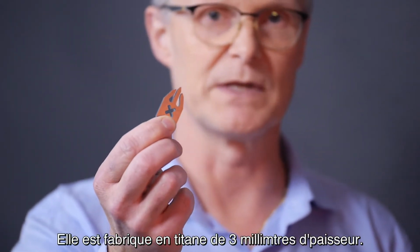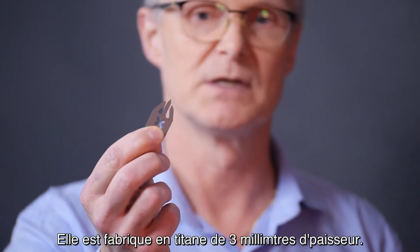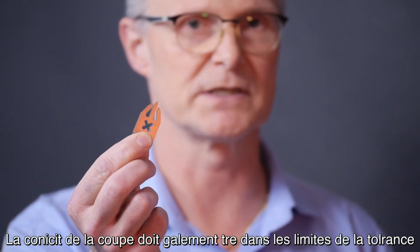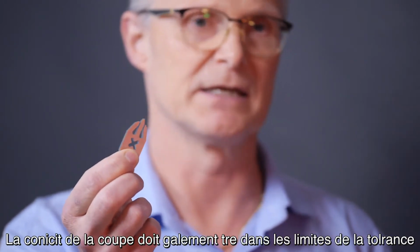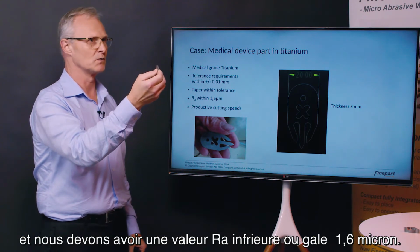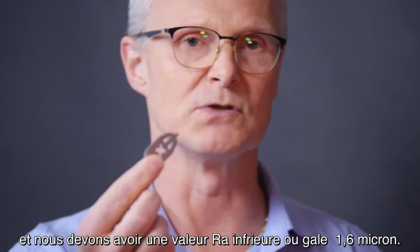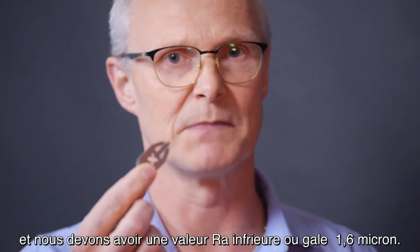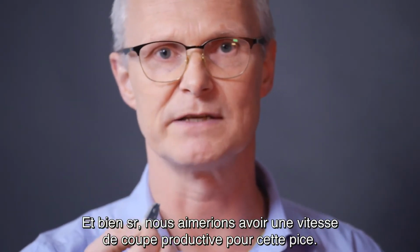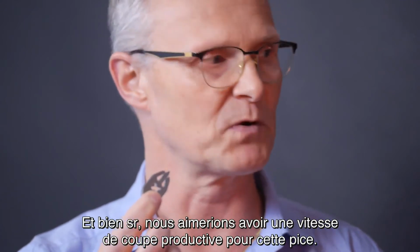It's made from 3 millimeter thick titanium. The taper of the cut must be within tolerance as well, and we need to have an Ra value below or equal to 1.6 micron. And of course we would like to have a productive cutting speed for this part.